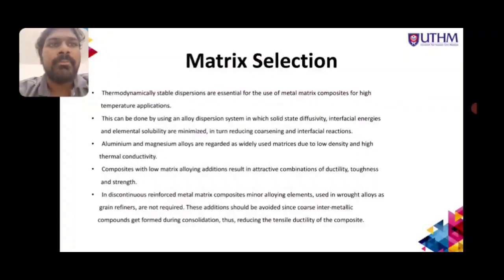For matrix selection, thermodynamically stable dispersions are essential for the use of metal matrix composites in high temperature applications. This can be done by using an alloy dispersion system in which solid state diffusivity, interfacial energies, and elemental solubility are minimized, in turn reducing coarsening and interfacial reactions.